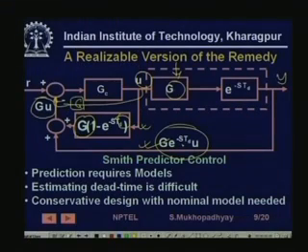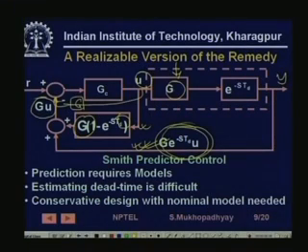That is the single reason for which feedback control is used. And if you take this feedback away, in the presence of modeling errors, this is not G to the power minus STD. So if you want to have the benefit of a delay correction according to a model, and also keep your control performance insensitive to modeling errors as well as disturbances, then you must feed back the measurement. You cannot just multiply it by G and send, because then you are going to be blind to the actual reality. If there is a disturbance, that will not be affected here.